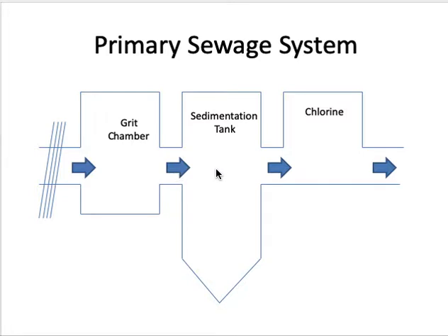So you have also the sedimentation tank. In this case, nagkakaroon ng tinatawag na settling process. Other than the heavy materials removed at the grit chamber, yung hindi na-filter dito will be settled down in the sedimentation tank. Kaya lahat ng magfo-forward in the next process ay yung water mismo na wala nang particulates, or medyo clear water na siya. So in the sedimentation tank, nandito yung settling process.